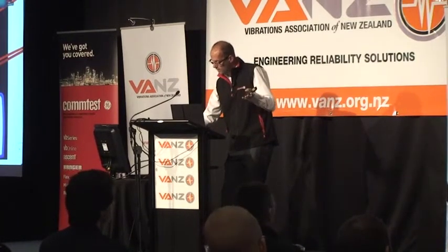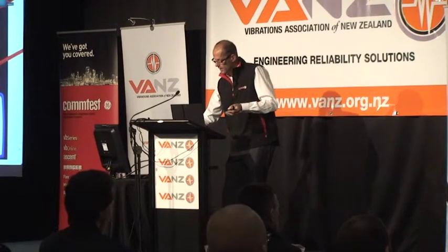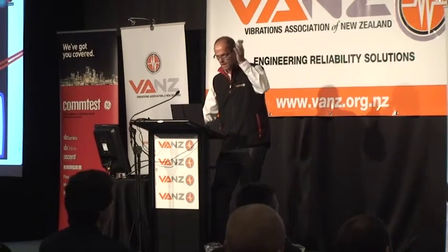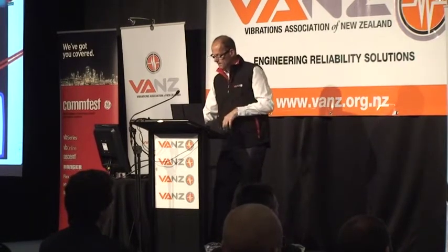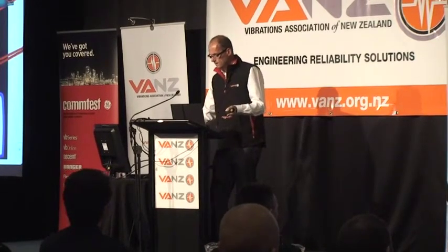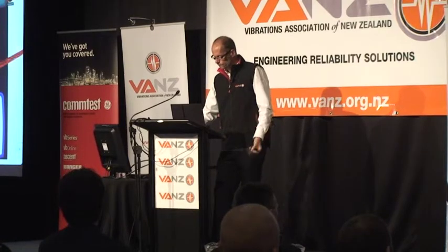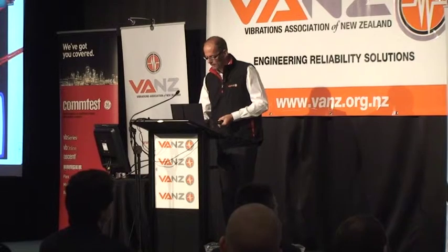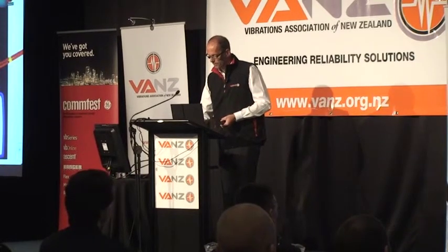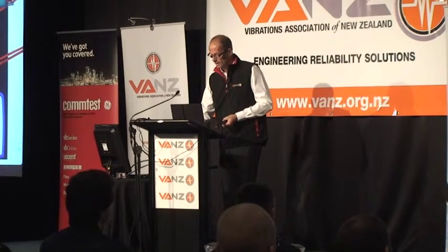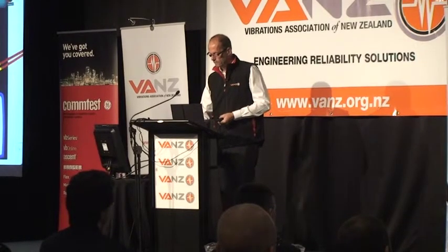So with the strobe, we can just detune it a little bit, so we've got it firing at a different rate, and now we see the belt flapping. We can see that one belt's okay, and the other belt's flapping. Very easy test to perform. We can change the flash rate and we can stop the belt itself. And we can see what's going on with the belt. So now you can see the little yellow marks on the belt aren't moving.